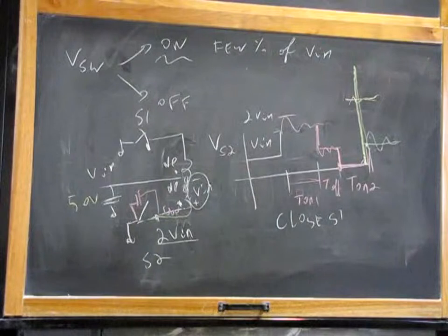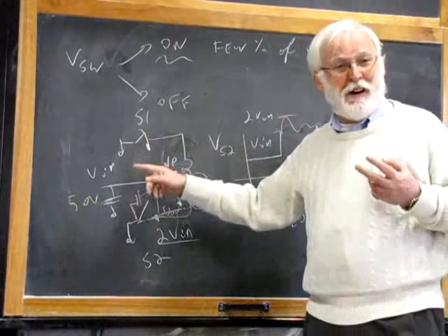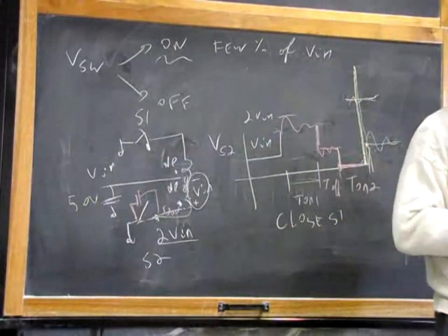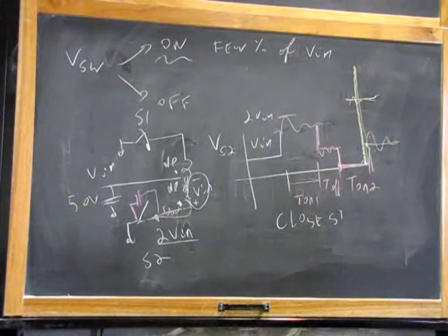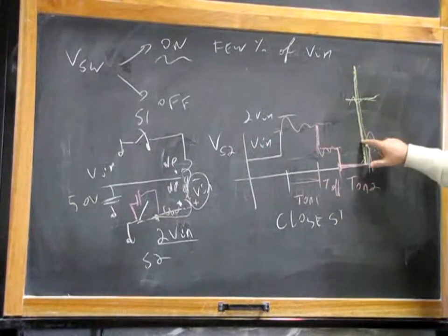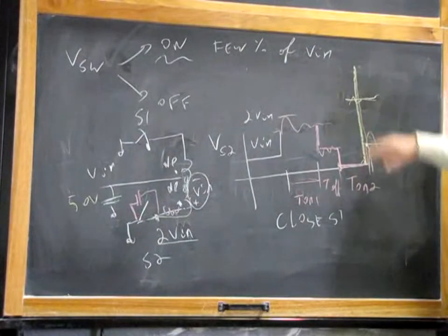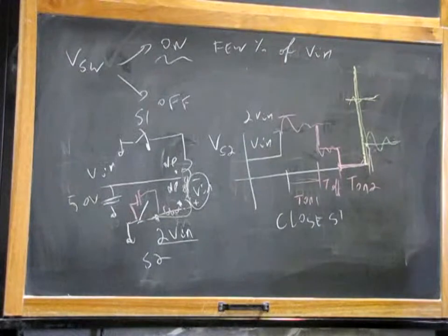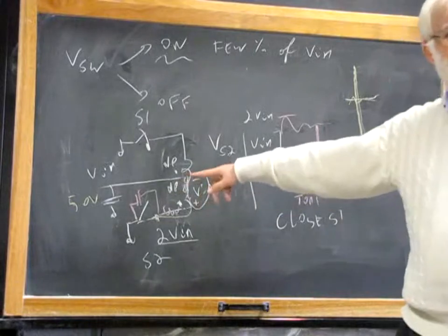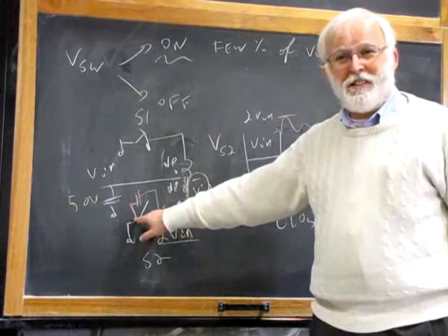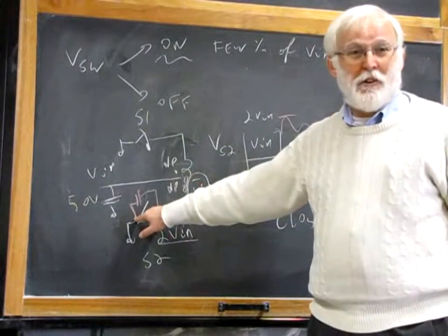They tried it, oh, it works, they went full voltage, full power. And guess what? There were two large MOS transistors each side, because each of these switches was made by two transistors in parallel, and they exploded basically. And I told them, be careful. Then we measured this voltage spike, starting with the low voltage obviously, and we found out that this voltage spike was around 6 times the input voltage. So if the input voltage is 50 volts, they got 300 volts on this transistor. That was a 150 volt part.